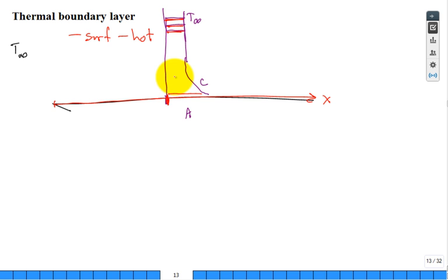Okay. So there you go. So this is the temperature profile. Well, you can introduce the concept of delta T. I was introduced to delta already, but delta T, what do you think delta T is? Thermal boundary layer thickness. What do you think the criteria is for the thermal boundary layer thickness? Within 99%.